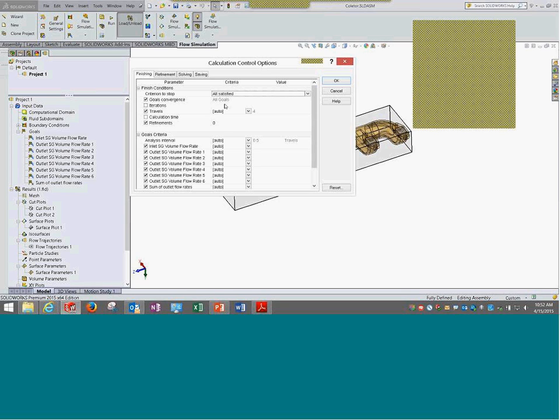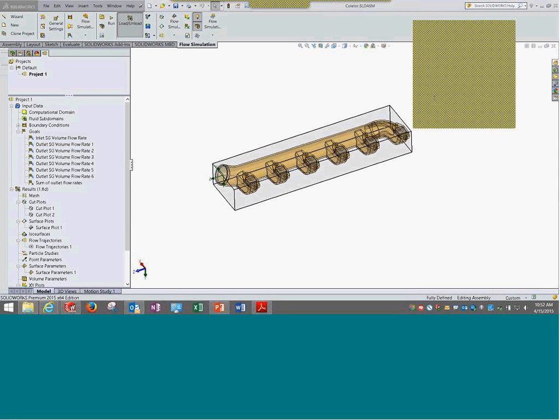This is important. Typically in flow simulations, remember the final results may not be final. The convergence plot is very, very important. Okay, what is the second question? I think I answered one of them: can we set the convergence tolerance? Yes, we can set it. This is the place where you set the convergence tolerance.